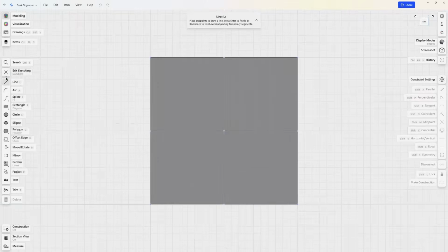Entering sketch mode defaults to the line tool. The small blue dot near the cursor confirms that a sketching tool is active. Move the cursor toward an edge of the block. Before clicking, a purple point will appear. This is a snap indicator. Clicking there connects the line to that edge, constraining it to move only along that edge's direction.